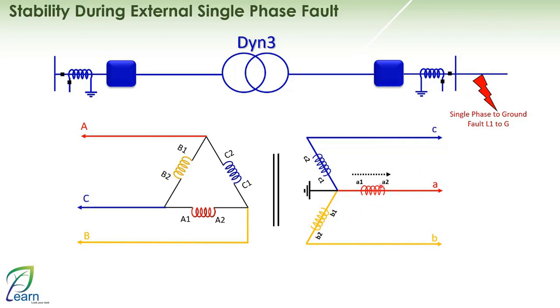Normally, the flux drawn from the red phase here will be countered by the red phase on the delta side. Correct, so the current will be drawn in this manner. Consequently, for the current to flow through this winding in the transformer on the delta side, it will flow through the external cables from phase B of the transformer and return from phase C.